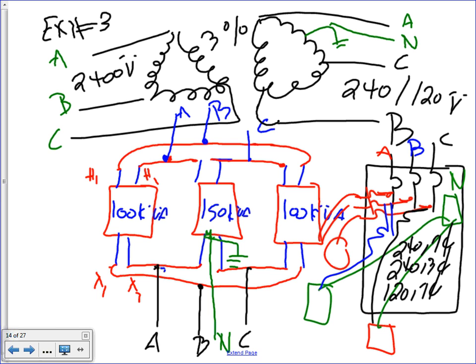For 240 three phase, you just take three phases, A, B, and C, and feed it to the motor. Now, 240 single phase, you just take phase A and B, or B and C, or C and A. Any two. Not a big deal. Do you have to worry about unbalanced loads with that? Yes, then you have to balance your load. Like if you have 6 of them, you have to stagger them between phase AB, BC, and CA. Good point.